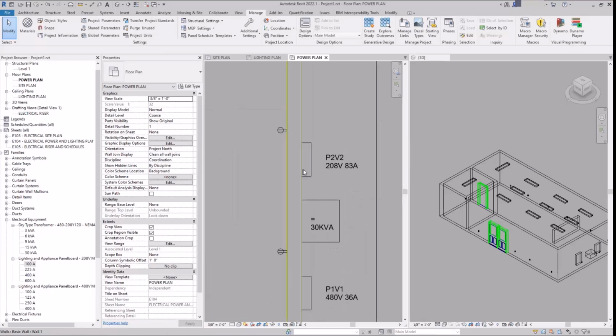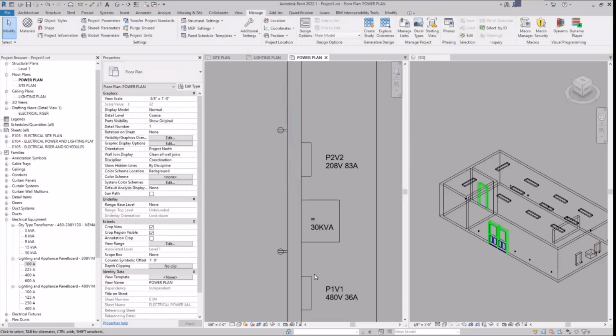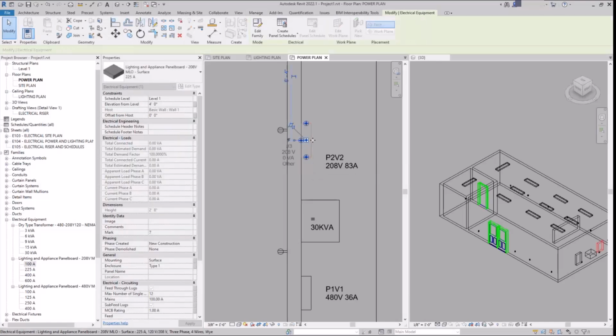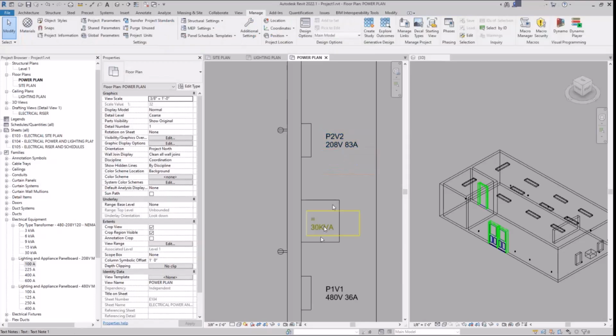All right. So we got a 208 panel board. Like I said, in this setup, we can do an MLO, which is main lugs only. So there's no main breaker in here. Since we're within the code requirements distance of all of this, and there's a whole big long thing in the NEC of, does this need a breaker or not? This scenario, it does not. I'm not going to get into when it does right now because it is very long and complicated, but just so that you know, this setup does not need a breaker right now.